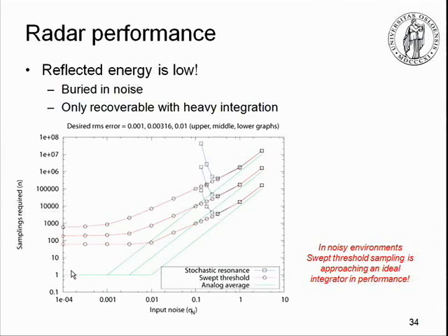at low noise values. Now, as I increase the noise of my signal over here, you can see that there are three different solutions depending on the quality. If you have really high quality, I have to start an integration early here, and I have to integrate. So these are the number of integrations, on an analog scale, that I need in order to recover my signal with some quality. And I have three different qualities here.